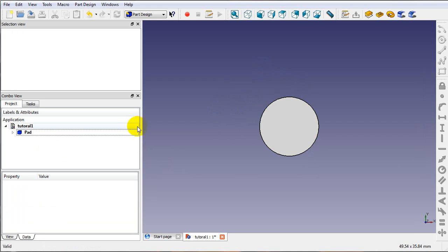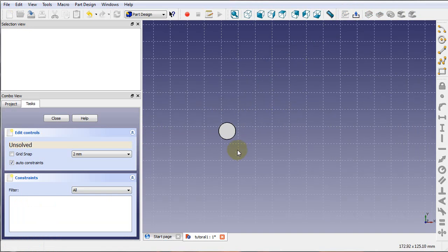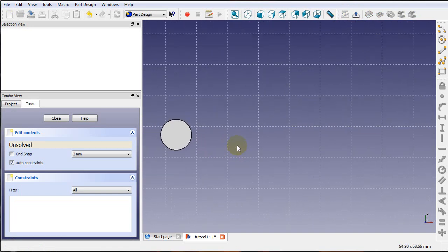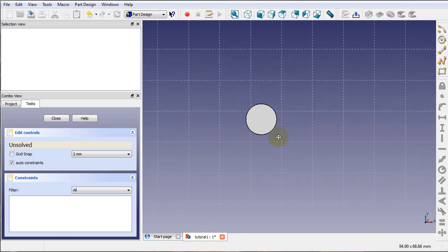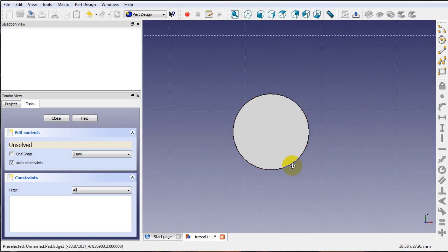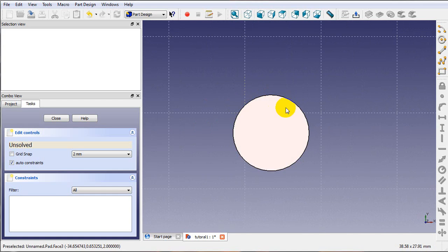Okay, so what we're going to do is go back to our sketch, which is up here on the right-hand side. It's in the same area next to the pad. Create a new sketch. Click on that. And you'll notice our drawing surface has reappeared. Let's go ahead and scroll in. Use the middle mouse button to pan over. Get it centered with your scroll wheel. And now we're not manipulating this. From here on out, we're going to create a whole new object.